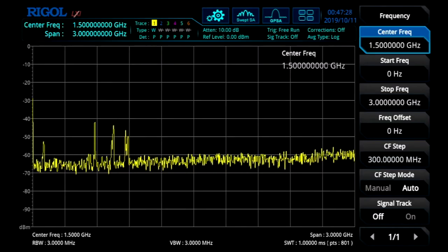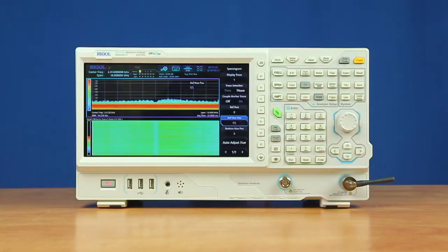our display. We can also set the instrument into real-time spectrum analysis mode, which gives us the ability to see more complex and intermittent signals due to the real-time bandwidth and very low POI. With 10 MHz of real-time bandwidth, seamless capture, and a 9.3 microsecond 100% POI, verify and debug the complete transmitter operation, investigate unwanted signal components, and sources of interference.